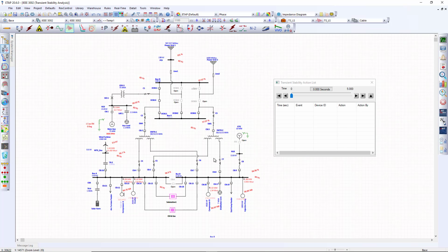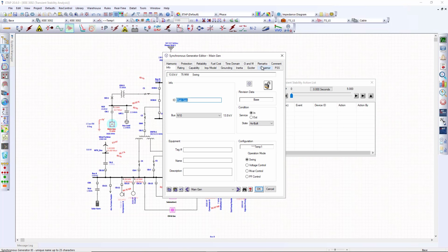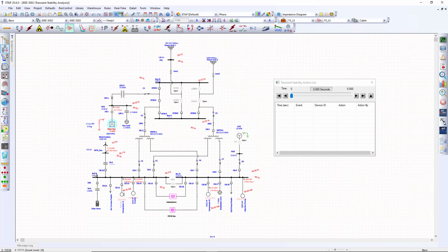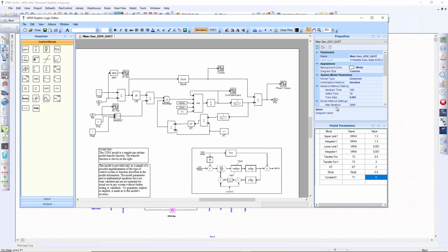And now, for the last example of today's presentation, we're going to be analyzing a load shedding or load rejection case. We will be paying special attention to the synchronous generator response after such an event, specifically to the governor, prime mover or governor system, for which we have simulated a UDM model. While we check the UDM model, we can start running the simulation. We have added several scopes so we can actually check the internal signals of the transfer function, and we're going to analyze the stability of the system based on the response of such UDM scopes.